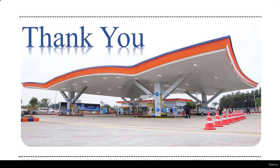Just now I have told you this, right? What does American wind have to do with India? No, just now I told you IS 875 Part 3 has the wind load specification. We have to take the wind speed from that code only, but the methodology will follow the American code.